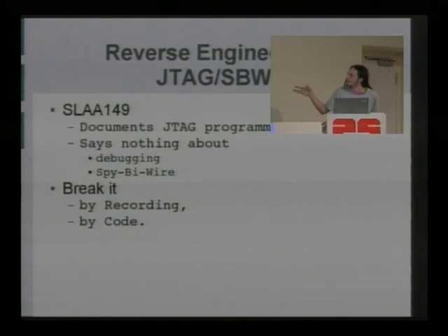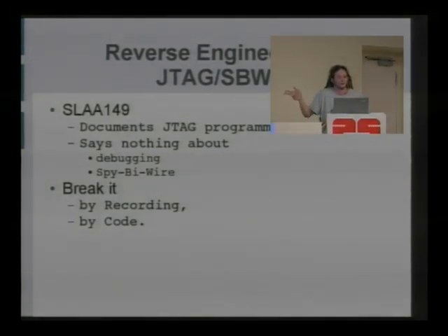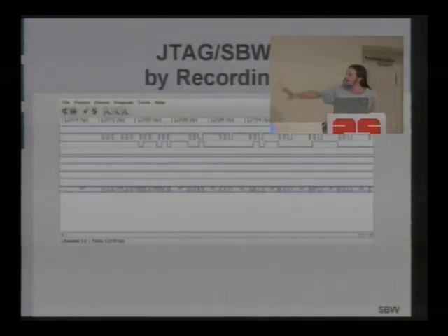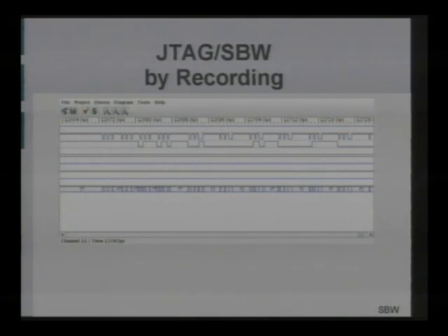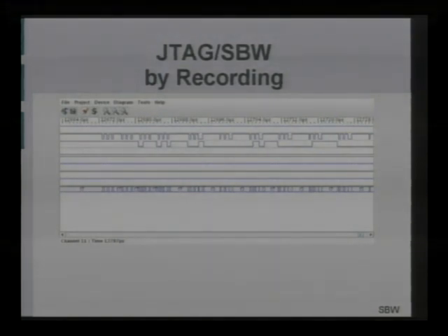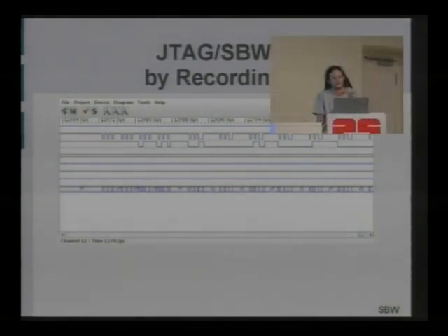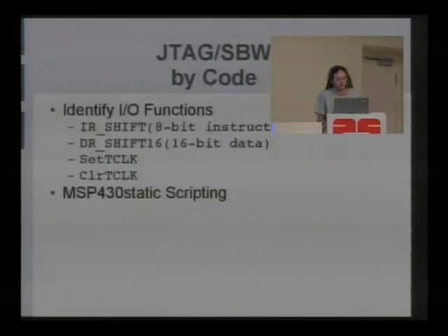There's work in progress to break this that I'm not the primary author on, but I can refer you to it if you're interested. This is the recording that I took of JTAG. And we have a tool now that the guy who's doing the JTAG reversing authored, which can actually parse this. So you can spit out from this recording a list of read and write commands to memory. Soon breakpoints will be supported as well.